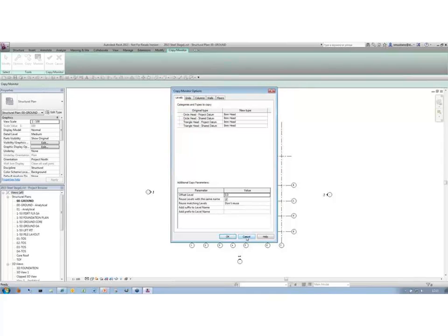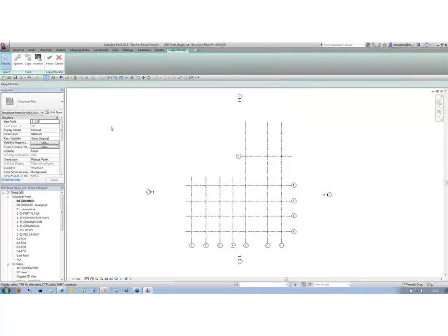So all this is pretty much set up as I want to use it. What I actually want to do is just take those grid lines and pull them into my Revit environment. So we use the copy tool, and then it's just a matter of picking these individually. And what you'll notice is you get this little heartbeat glyph appear after I've selected the particular components. And this just identifies that we've copied it into the Revit Structure project, and we're now monitoring it.